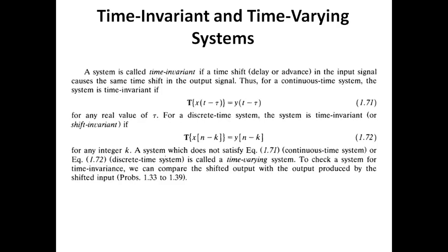both the analyses will be different. So whatever output you are getting should not be dependent on time, and this is what is called time invariance. If the processing varies as you delay or advance the signal, or in other terms, if you shift the signal, then it is regarded as a time varying system.